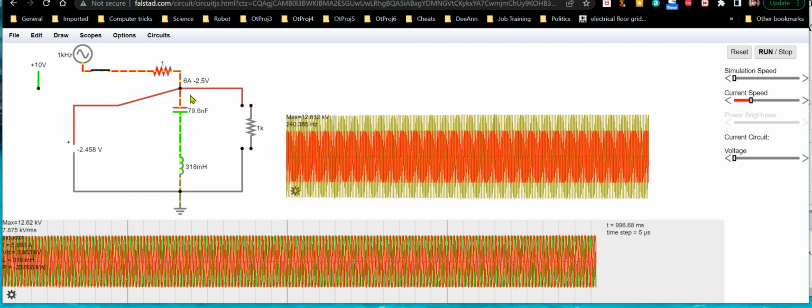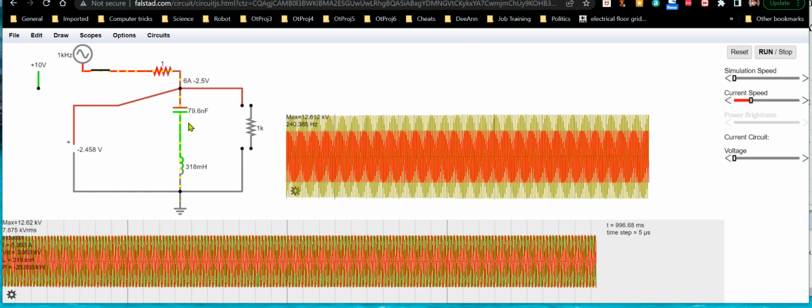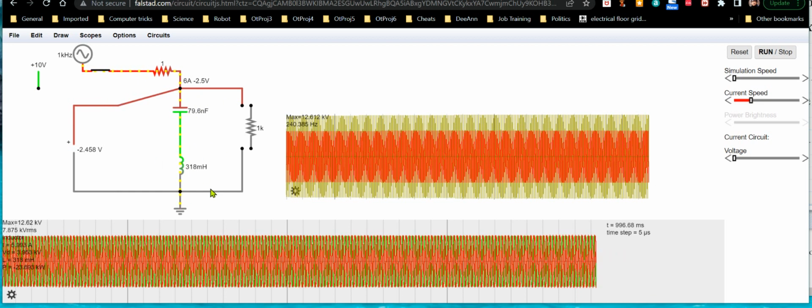But anyway, here we have current flowing through it constantly, but in a parallel resonant circuit, if I were to put the tank in here, you wouldn't see any current flowing through it, because resonance is when it's at maximum resistance. So basically no current would be able to get through. But here it gives you maximum conduction, because they're at resonance in a series resonant circuit.